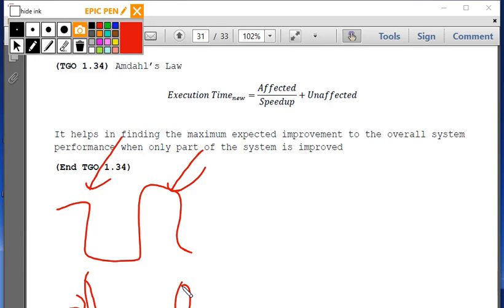Now, it holds the value, and 3 nanoseconds later, it gets rid of the value that I wanted, right? So there's a potential that after 4 nanoseconds, the value has changed for some reason. Now, if I improve the performance of the architecture by 4 nanoseconds, that means I'm shifting this all over by 4 nanoseconds. And if I don't account for this at the I/O level, the result is going to be that you can't guarantee proper execution of the computer. So being able to tie this to I/O, to interfaces, to underlying computer architecture is actually very important.